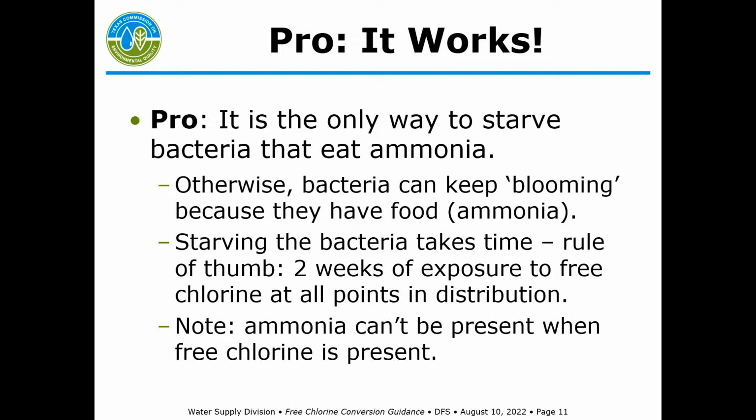Just a little bit of exposure to free chlorine isn't enough to kill those bacteria. You actually have to give it enough time to starve the bacteria to have an effect. So that's that rule that we have here of 2 weeks of exposure is a good rule of thumb. And that means 2 weeks at all points in your distribution system. If you start it and it takes 5 days for the water to get to the end of your distribution system, you start counting 2 weeks from that point on. That's a good rule of thumb. And then, of course, you'll have the time you need after that to restore it back to monochloramine.